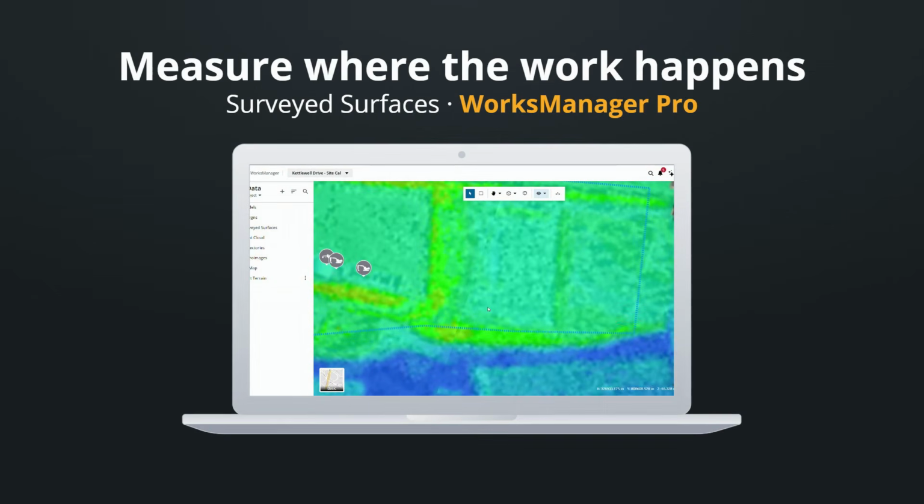That's surveyed surfaces in WorksManager. Import your TTM, tag it as surveyed with the date it was captured, and it aggregates itself into one live terrain the whole project can rely on, filterable by date and by source whenever you need to check.